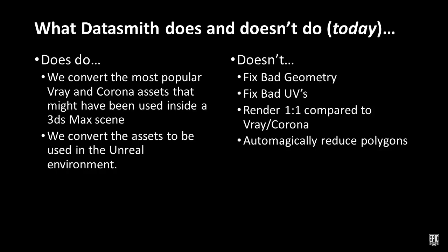You want to avoid overlapping vertices. You want to avoid isolated vertices and long triangles. You want to make sure that the smoothing is appropriate and that the surface topology will accept good-looking textures. It's worth noting, though, that the CAD importer will have some topology tools that may fix common issues that are usually found within CAD workflows.